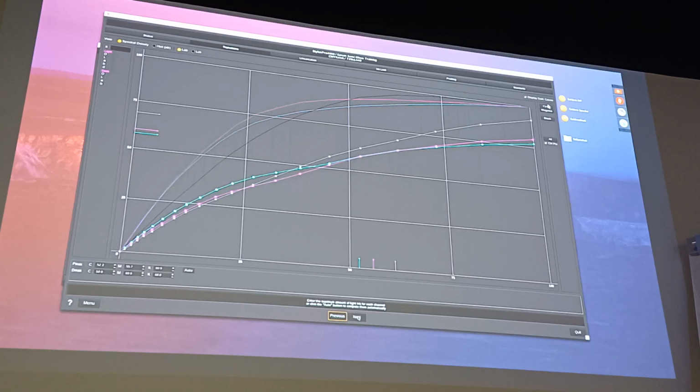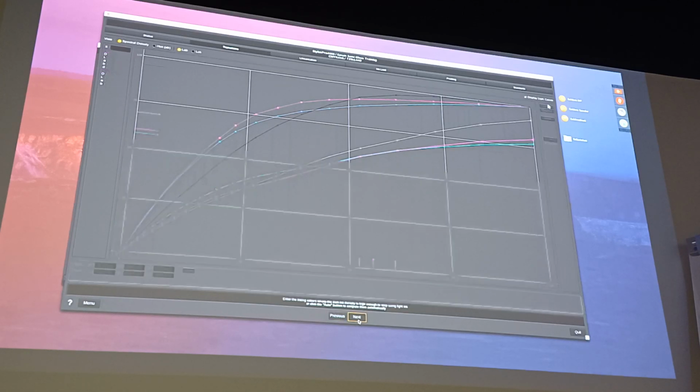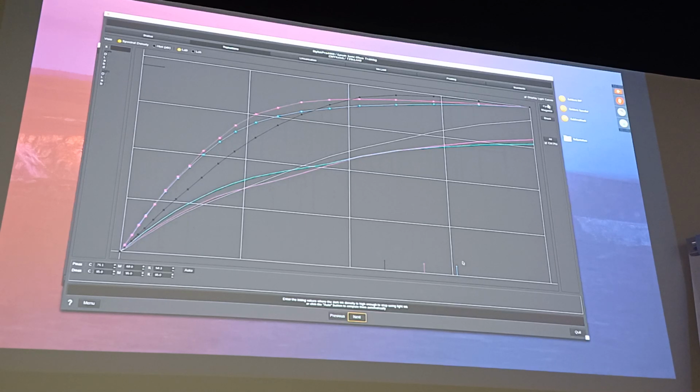Here you can see that Caldera is pushing auto limitation. This is the vector that you can see here on the bottom, and we can see that all the dark inks have been clipped at 95% by default. Why not 100%? It's just to have extra margin for linearization later on. This is the maximum Dmax by default.